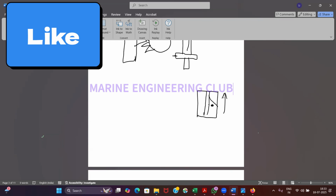So that means my plunger will be going up and down. Agreed? And if the plunger is going up and down and my spill port position with respect to my helical groove is in this position, that means the stroke will always be there and fuel will always be injected. But if the helical groove position is in this slot, then this is a complete groove through and through. Will there be any compression of fuel or rise in pressure of my fuel happening?